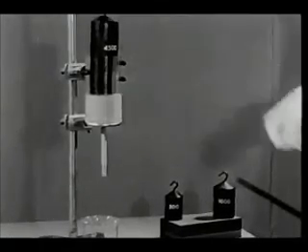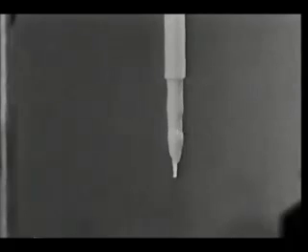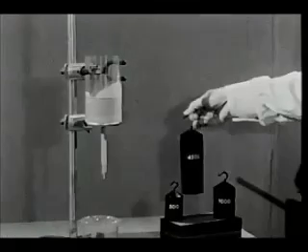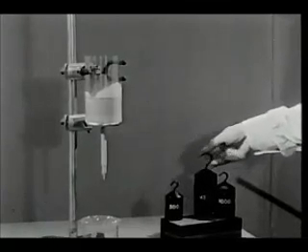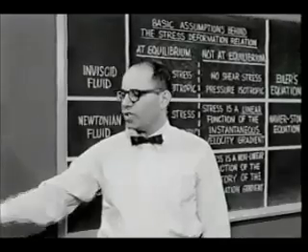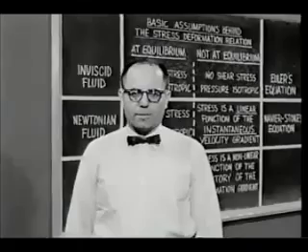A much larger weight. The flow is fairly rapid. I take the weight off. The flow stops. In a state of equilibrium, this material can support a shearing stress up to a critical value called a yield value. Even with materials not having yield values, the Newtonian fluid cannot explain many flow phenomena.